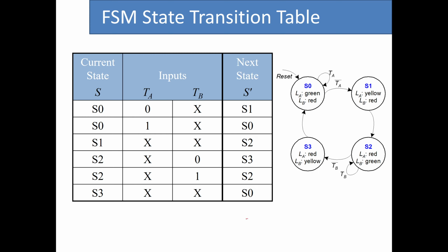So in the design of the Moore FSM, if you remember, we had the register here, we had this next state combinational logic unit, and we had some inputs, and then we had this as the feedback from the current state to the combinational logic circuit that calculates the next state, right? So we want to find out this part of the circuit now.